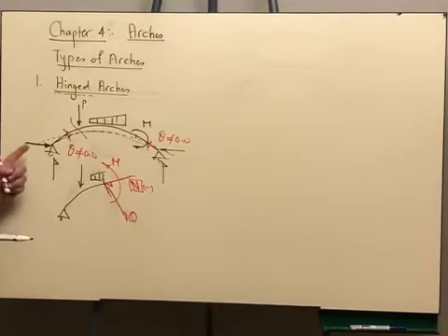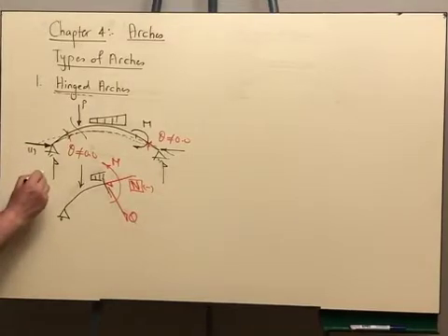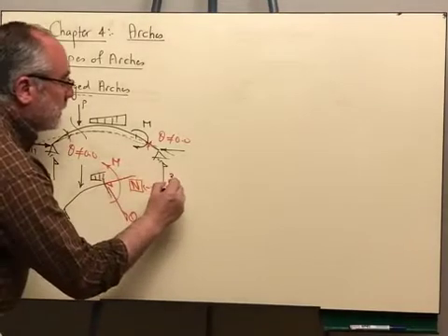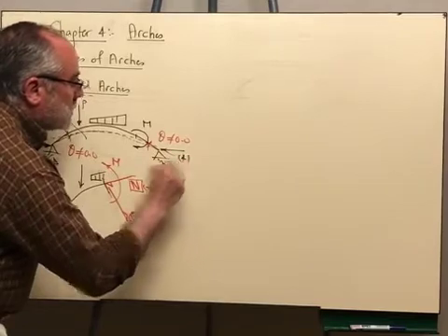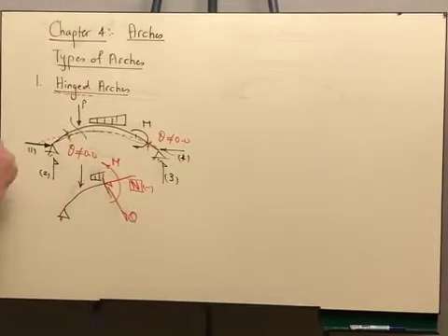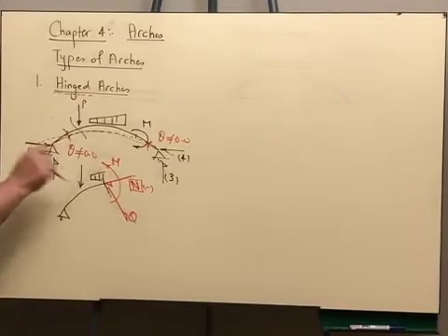Okay? This type of arches is statically indeterminate, because if we count together, how many reactions do we have? We have 1, 2, 3, and 4 reactions. We are having 3 equilibrium equations, no condition equations, so therefore this is once statically indeterminate.